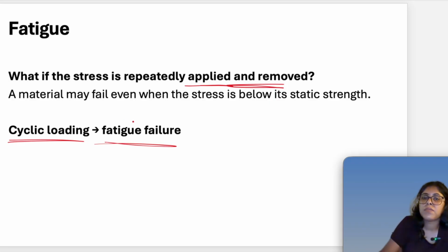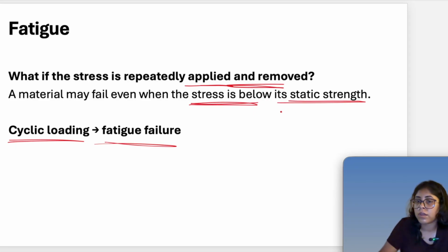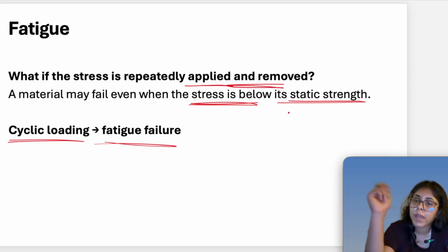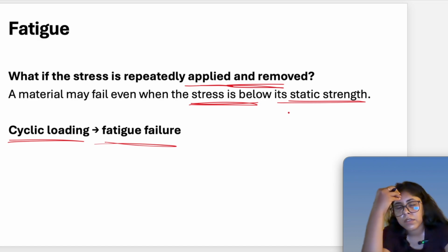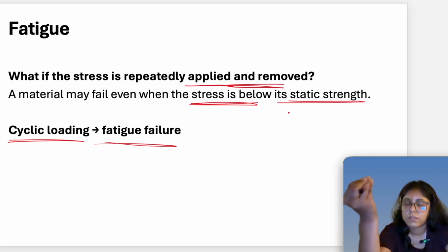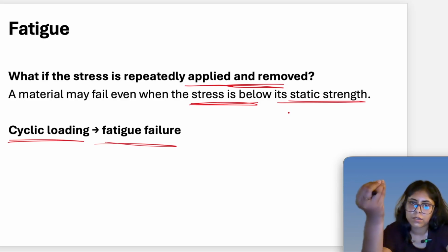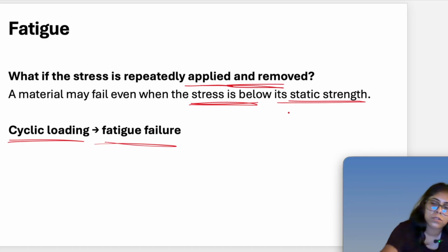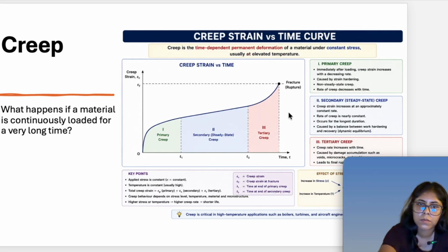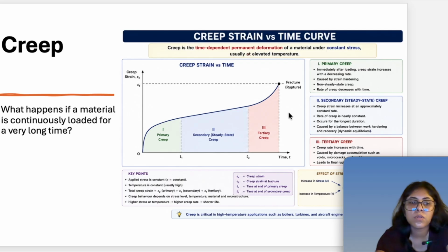So material may fail even when the stress is below its static strength. Even if you are applying a lower stress, but you are loading it with that lower stress and then reloading, load and reload, load and reload, then even if it is very low, the material can fail by fracture, fatigue, right? So yeah, and then we come to creep.